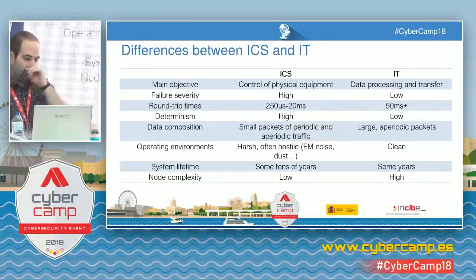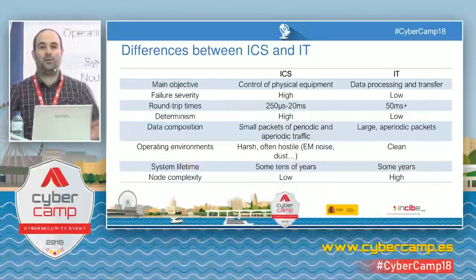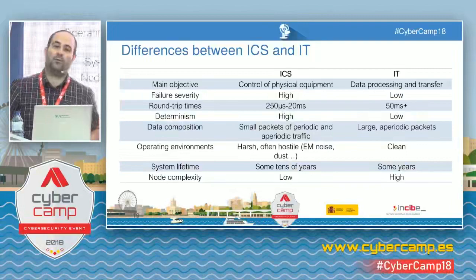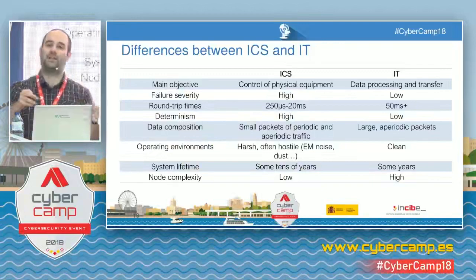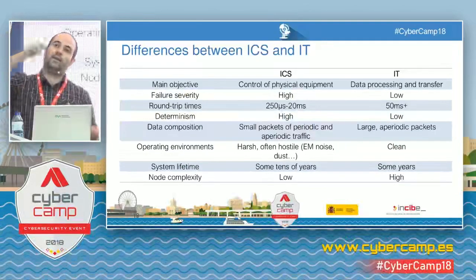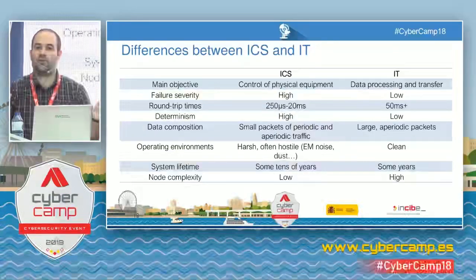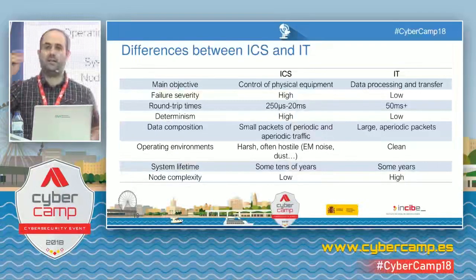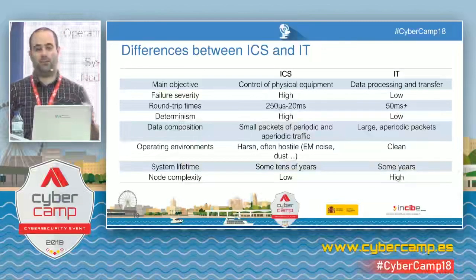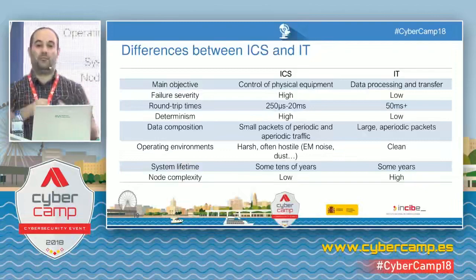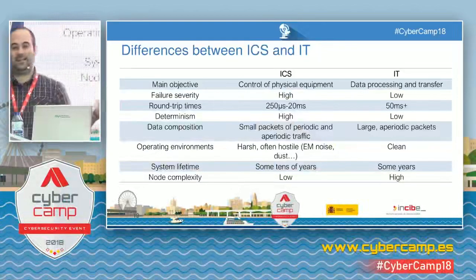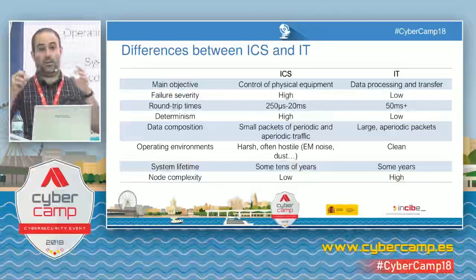Industrial networks also have other differences and peculiar elements. There we don't have users that go to see the newspaper early in the morning. All that traffic comes from PLCs, the ones saying to the control server, this is the temperature, every second, I don't care, it'll stay like that. And every now and then the operator will do something, but industrial networks are much more static and deterministic than the IT networks. Topology never changes, contrary to a Wi-Fi network where users log on and out at all times.